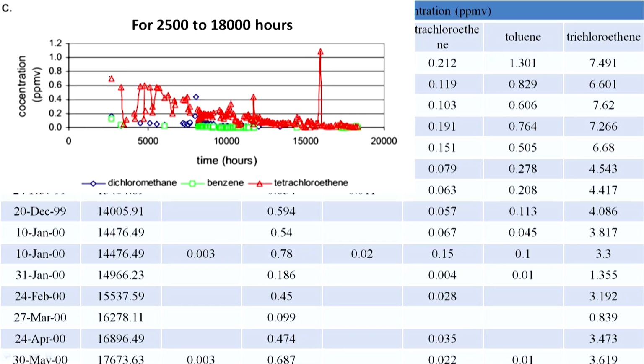I will stop pumping for some time and then let the system reach equilibrium between the soil, gas and the aqueous phase, or at least try to have more contaminant now in the gaseous phase, and then I will pump out that particular contaminated gas. So, that is why you see these particular rebounds, and I guess they stopped pumping, or there was some particular reason why there was considerable rebound out here, right.